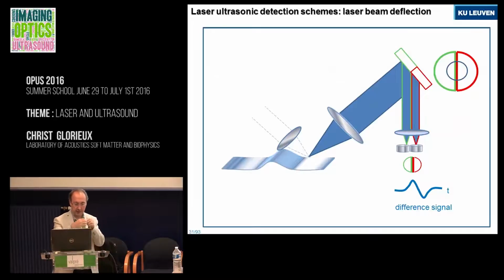In this case, it was excited, for example, by focusing the light with a cylindrical lens to a line. But the signal is bipolar because it's the slope, the spatial derivative of the wave. That also means this technique is more sensitive for short wavelengths or sharp waves than for smooth waves. If you convert to time, it's more sensitive for high frequencies than for low frequencies. It's a high pass filter response. So it's not so suitable for slow phenomena and long wave packets.